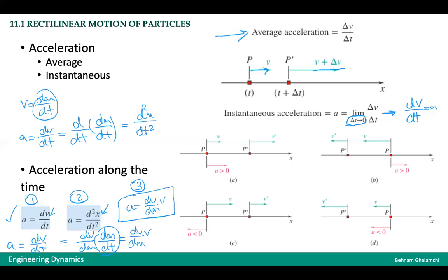Sometimes in some problems, the given inputs and required outputs are only acceleration, velocity, and displacement, and nobody talked about the time. So in this case, I recommend you use this formula for the acceleration, because in this third type, there is no time. It's all about acceleration, velocity, and displacement. So in those examples, you should use this type of definition of the acceleration.